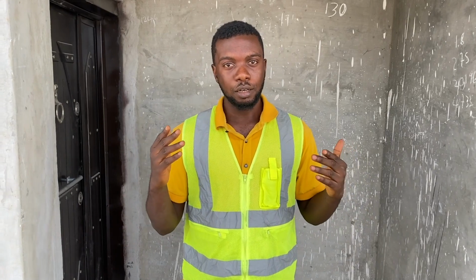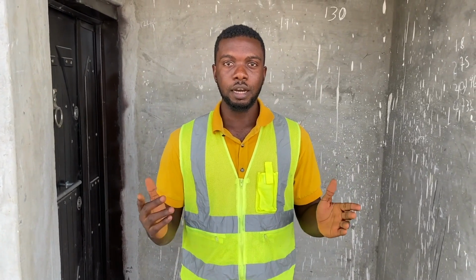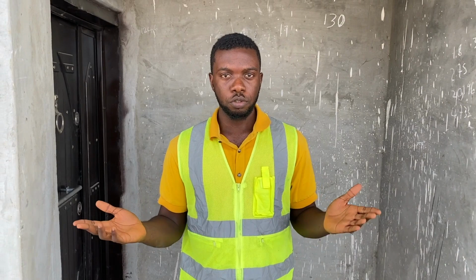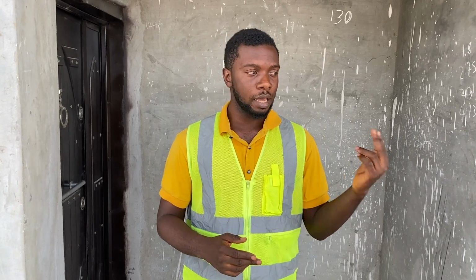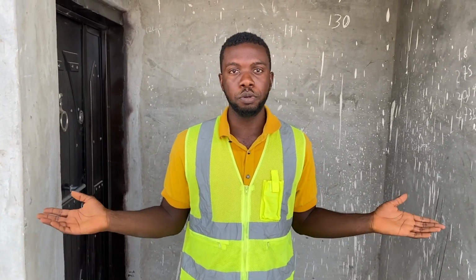It tells you the type of foundation you're going to use. It determines the load bearing capacity of your land, and it designs a kind of foundation that will fit that type of structure and the land you're going to be building on, so that your building wouldn't collapse. So mostly when you hear people say building collapse, it is because they do not know the soil type they are going to be building on, and it's just built for building's sake. So all this you have to make sure you're checking.